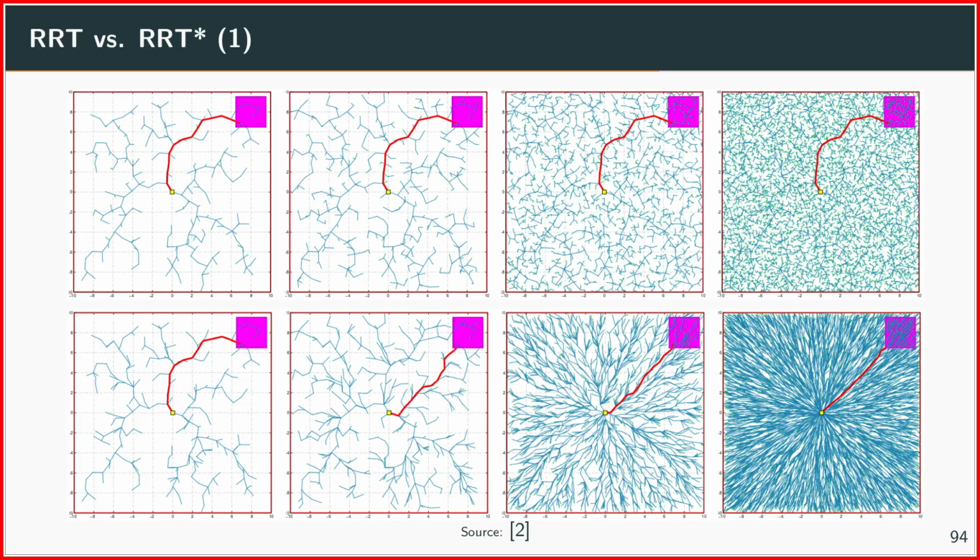And if you come very close to it, you can say, okay, it cannot get better. But we could do the same with the normal RRT, just calculate, I don't know, 10 or 100 paths and then compare the costs. Yeah, you can definitely do that. But in very complex scenarios, you really need to have all the points sampled along this line here. And it would be very, very lucky to get there. You will get there, but it would take a lot longer than just running RRT star.